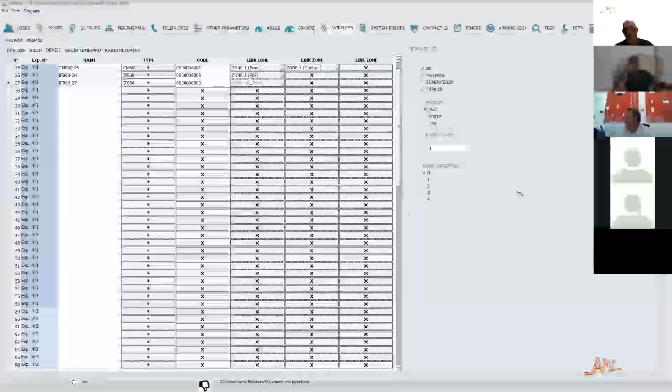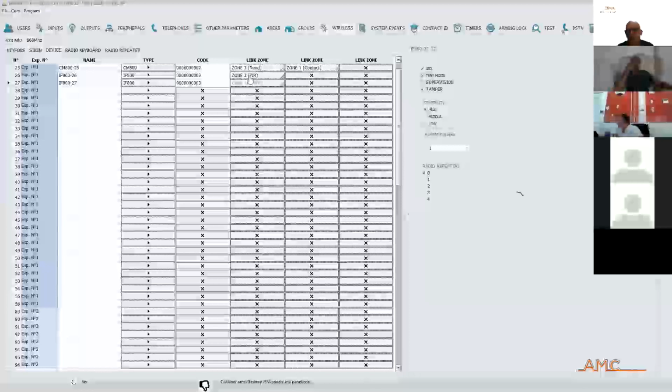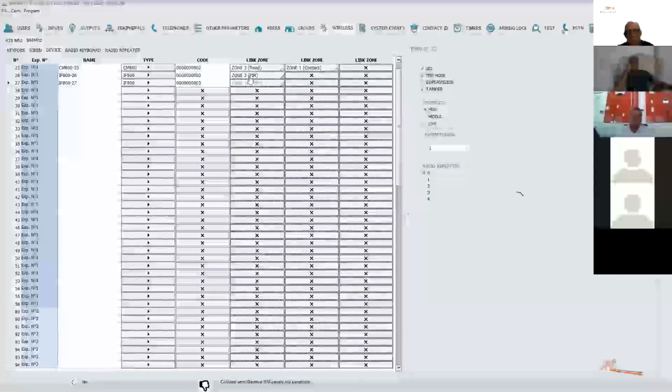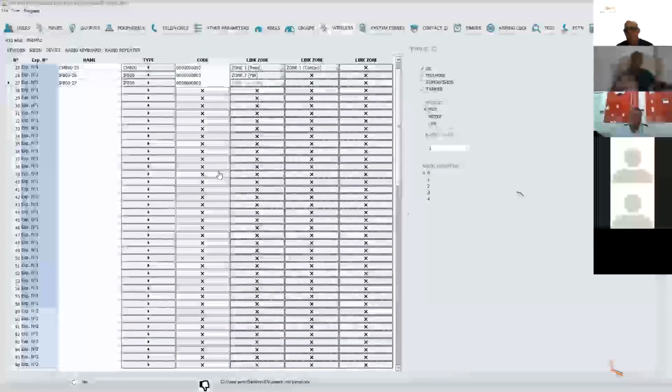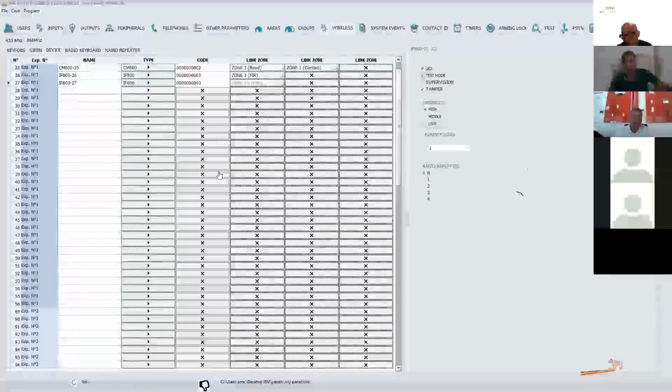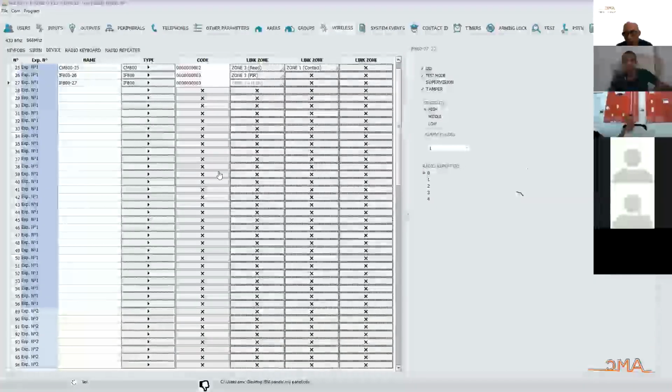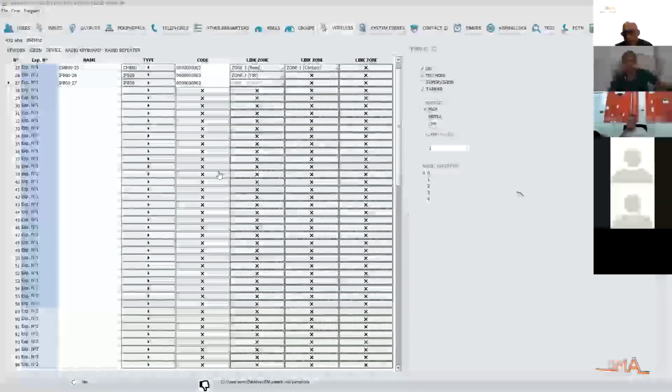Of course you cannot recognize which sensor goes into alarm. But if you need to select the same wired zone with different wireless devices, we leave this possibility only for one reason: in a few cases you have, for example, more PIRs, but the zones are finished, and you need to add only one PIR.